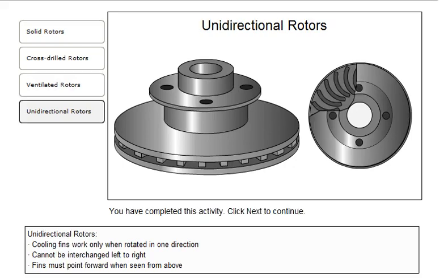In some ventilated rotors, the cooling fins are curved or at an angle to the center. The fins only work properly when the rotor rotates in one direction. These rotors cannot be interchanged from left to right. The fins must point forward when viewed from above.